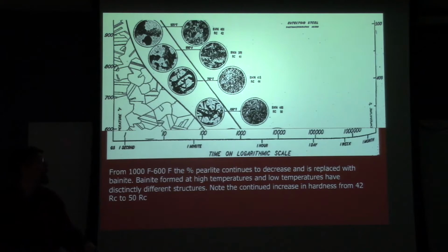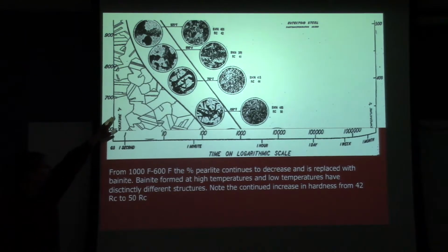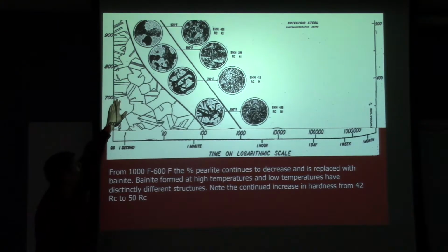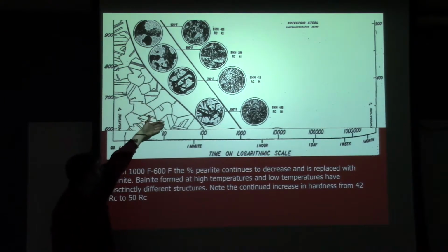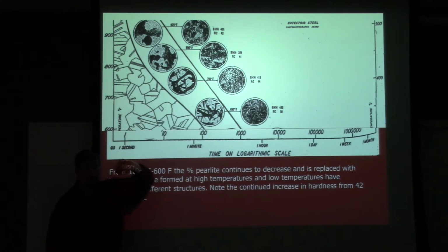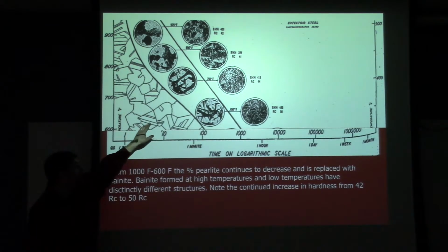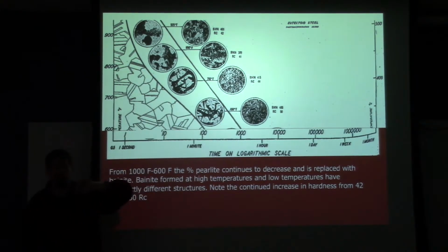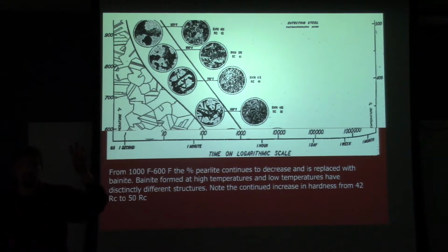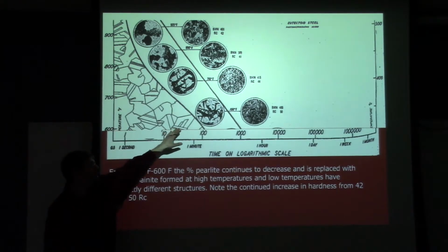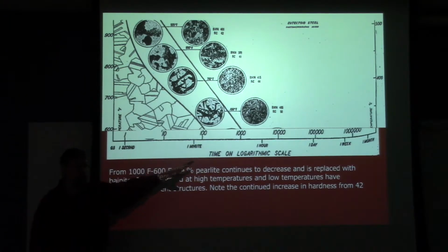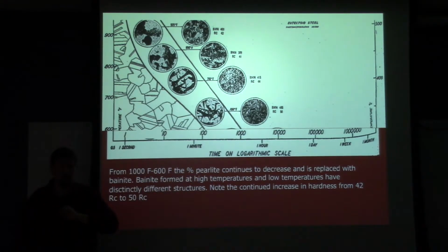Now, if you can get it below that temperature, let's say you can get it down here to 700 degrees, well, now you'd be able to hold it for 10 seconds or something like that. You've got more flexibility. And you'll see that as you go to lower temperatures, you've got more and more time. So that gives you the ability to initially quench rapidly, then slow down my quench and find some temperature that I might want to hold at for a while to allow some structure to form, in particular this bainite that we were just talking about.